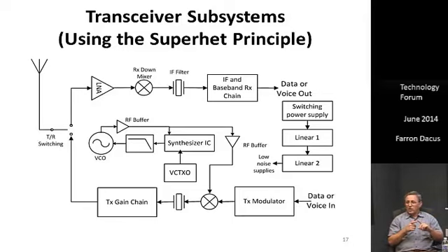Now then, there are two ways that you can seemingly improve this capability when people say they're going to the theoretical floor. One is that you need a certain amount of signal-to-noise ratio to demodulate. Now it's typically 10 or 11 dB. But through error correction, there are modern error correction techniques that reduce that quite a bit, maybe 4 or 5 dB. You get down to 6 dB or so being the required signal-to-noise ratio to get a good bit error rate.